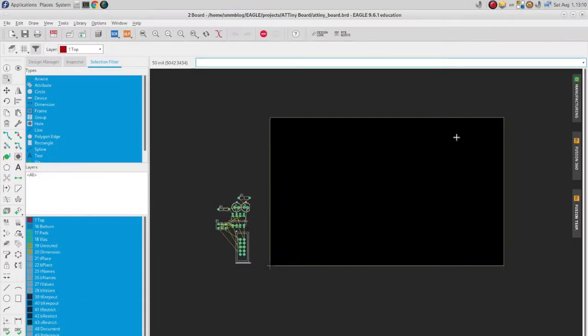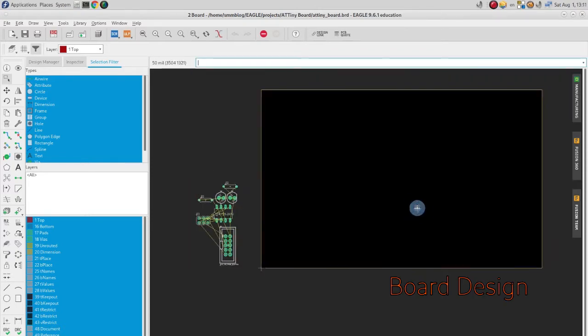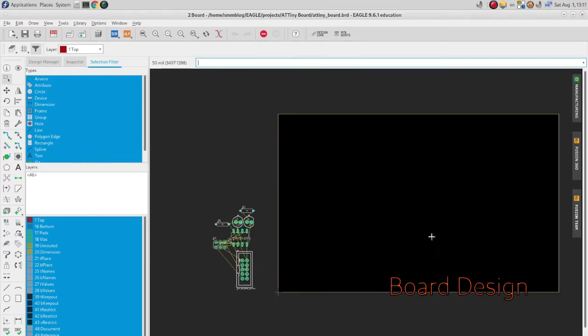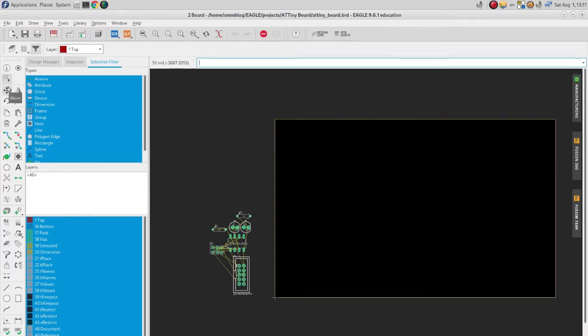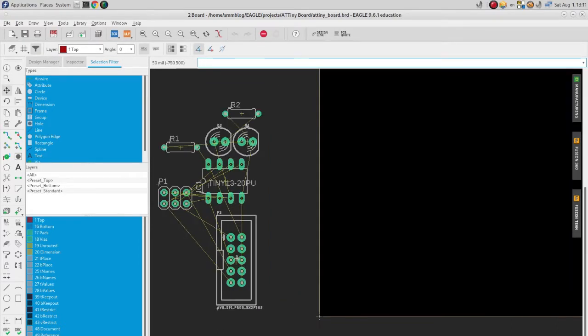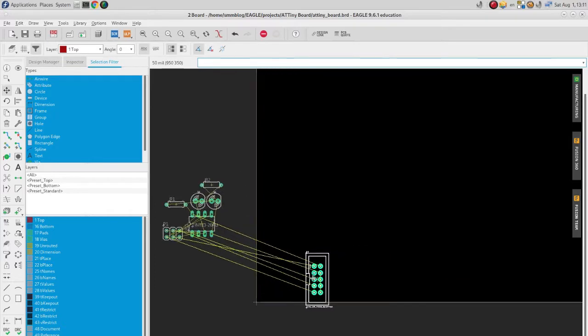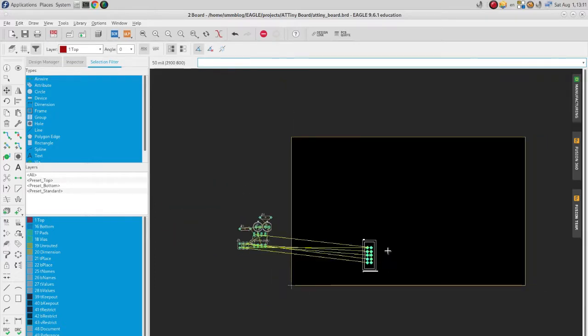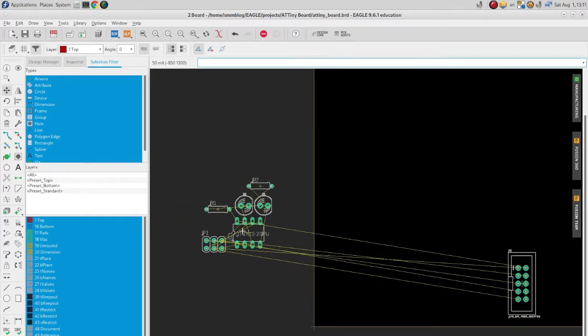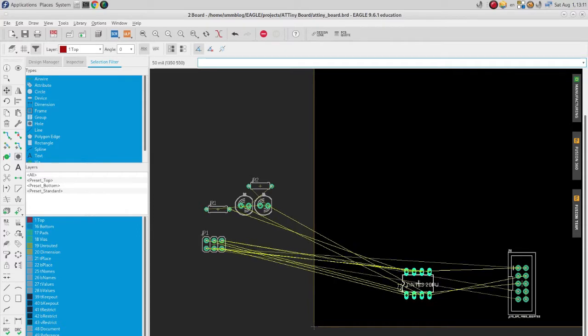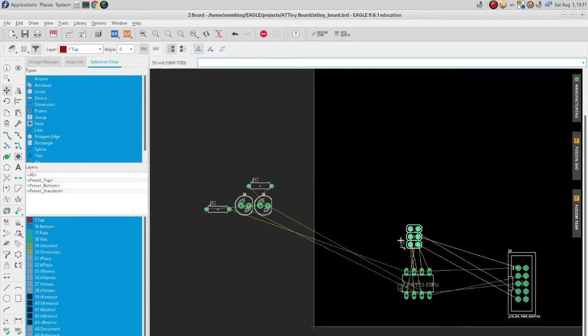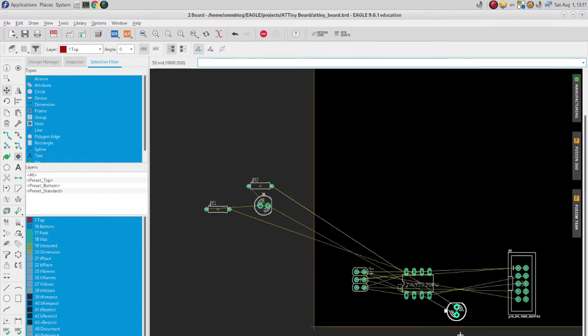Now let's talk about the board design, which is interconnected to the schematic design you made or will make. Here in the board design everything is important. This is going to be the shape of your PCB, and here come the limitations of your design. First and most important thing is to lay out your components as near as possible to each other to facilitate everything. Also keep in mind that our design is going to be a single copper side design.